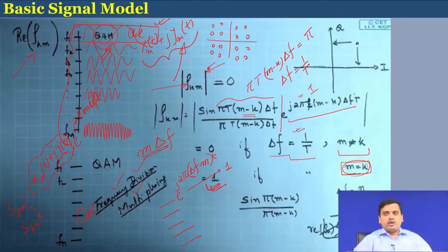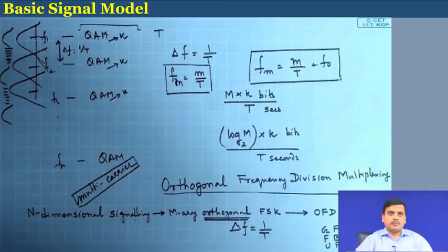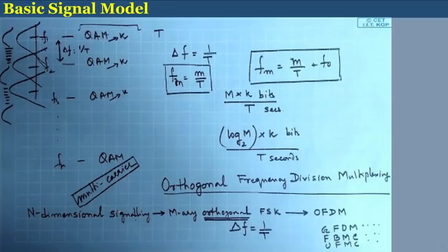So, that is why whatever we have analyzed over here forms the foundation for whatever we are going to discuss in the future lectures. Okay. So, now at the receiver side, as we have clearly said, we are going to do this operation, and although these frequencies are overlapping, still because they are orthogonal to each other by virtue of the orthogonality criteria, they can be decoded without any interference. So, this is orthogonal frequency division multiplexing, which I have just explained in the previous few minutes.